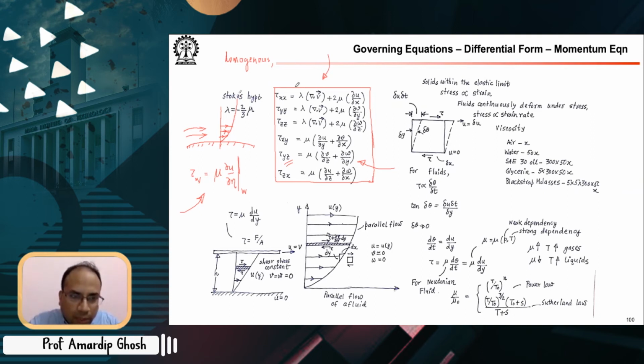And isotropic. Remember that the derivation of this, with fourth order tensor algebra, is involved with the assumptions of Newtonian fluid and isotropic behaving fluid. Isotropic behavior means the properties are the same when evaluated in different directions. For example, you might think of the refractive index of a fluid.